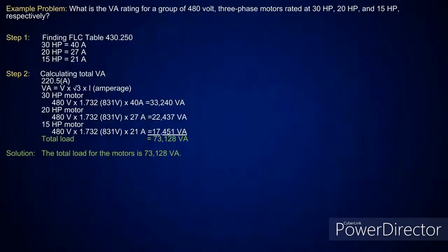Now we're done with 4 loads. Now we're going to the 5th load. Here's my motors. All my motors, what am I going to take them at again? 100%. Yep, we're not doing 125 on any of these yet.